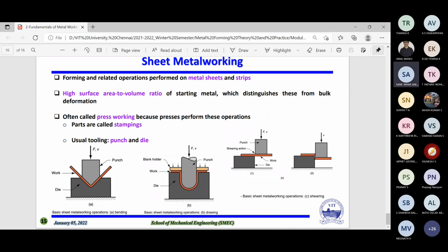Yeah, there's a question with the shearing itself, the unsupported part. What is it supported by? Because when the punch is pressing hard, the entire thing would topple to one side, right? This is a cantilever. A cantilever is where one side is supported by the die and the other side is not supported. So you have to cut. If you have support, then how will you cut it? How will it fall down? And this punch will not fall. There is some support, because this is only a schematic diagram.